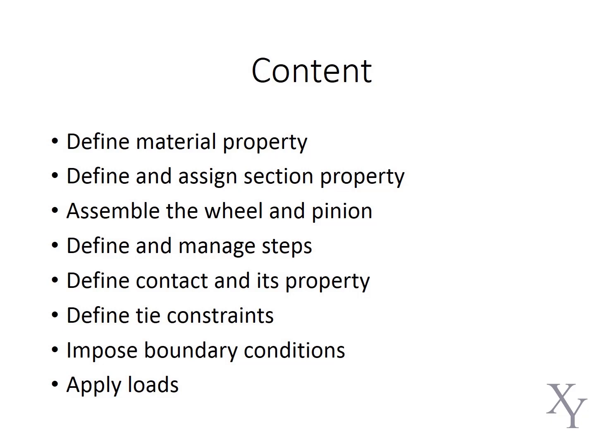the wheel and the pinion parts, and define and manage steps, contact and its property, and define tight constraints of the property of the part, and impose the boundary conditions to the assembly, and finally apply the loads.